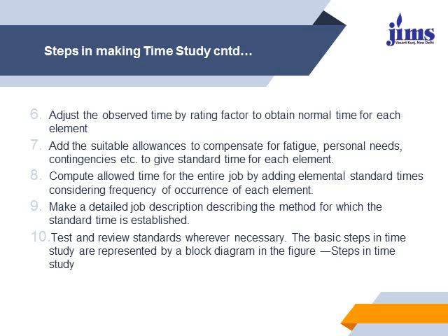Add the suitable allowances to compensate for fatigue, personal needs, contingencies, etc. to give the standard time for every element. Now compute the allowed time for the entire job by adding elemental standard times, considering the frequency of occurrence of every element.